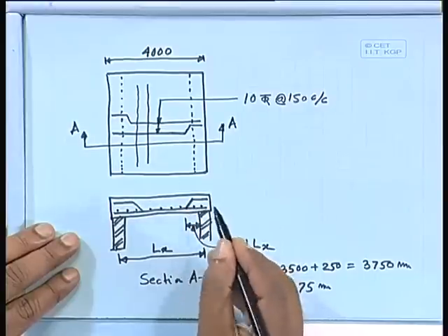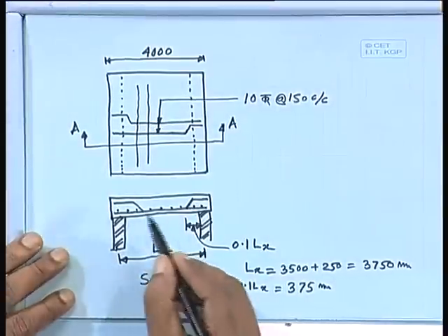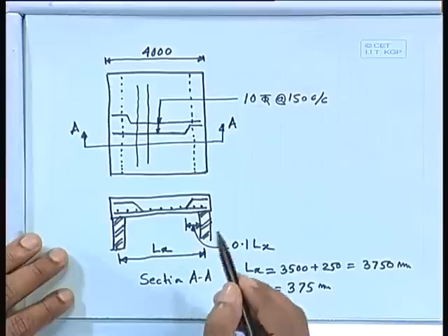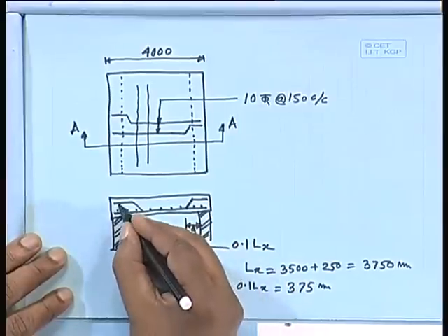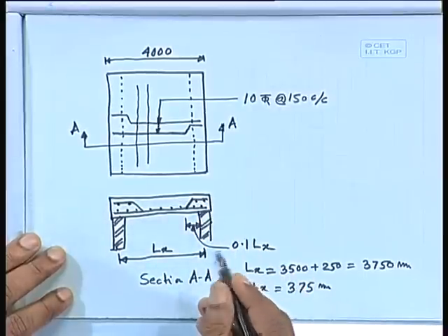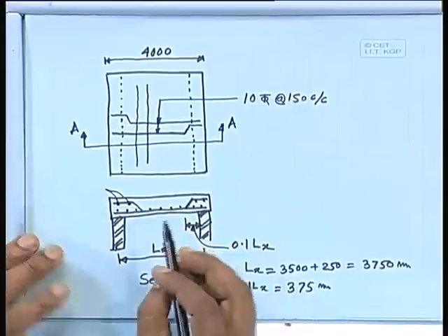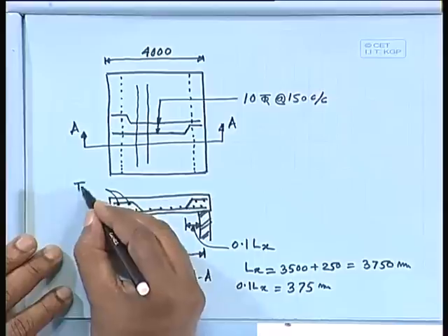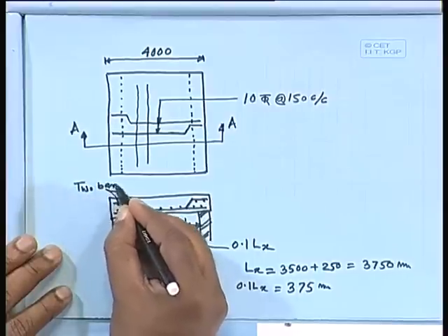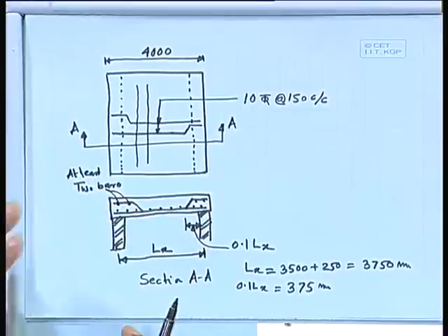We shall get it like that, because all the longitudinal bars in the other direction are cut, so we will get the circular one, with respect to the bar diameter. And similarly at the top also, please note we have to provide at least 2 distribution steel bars at the top to hold it. Even if it is small, you have to provide at least 2 bars.